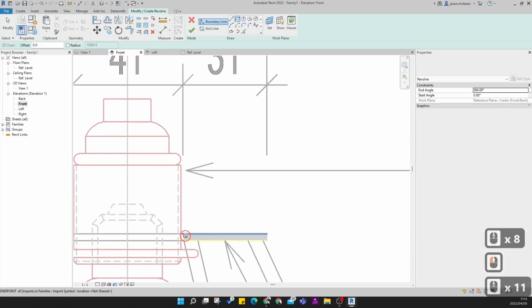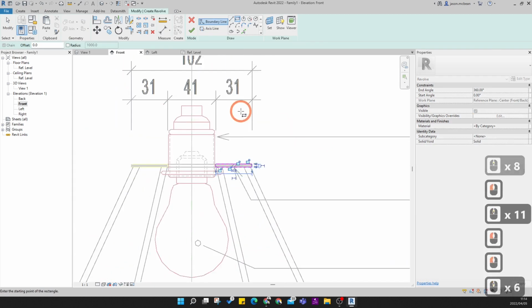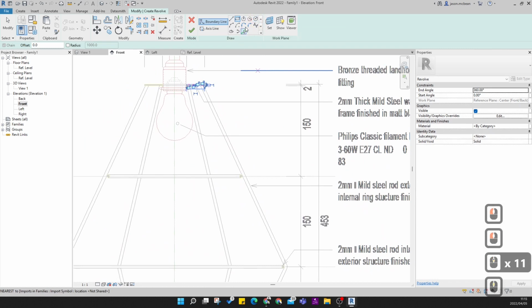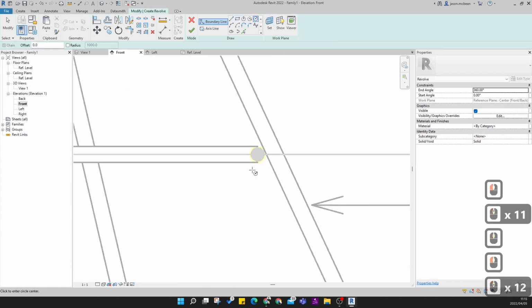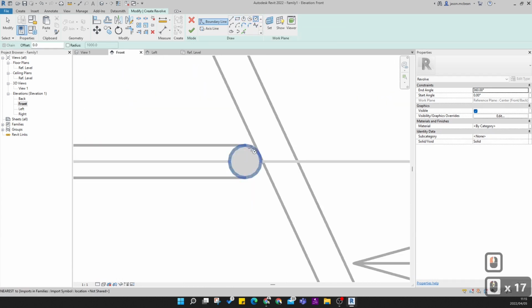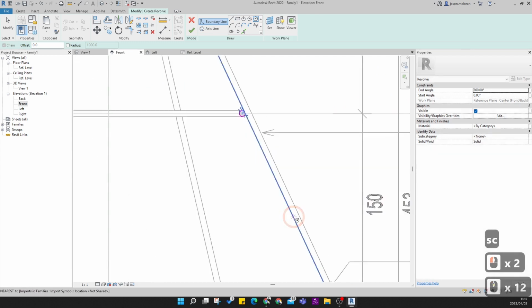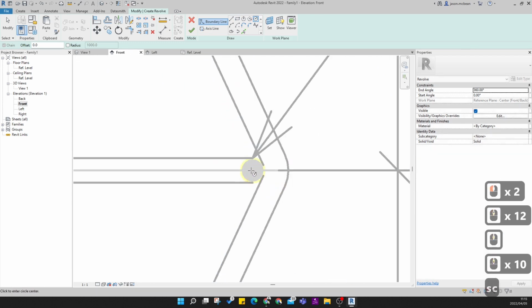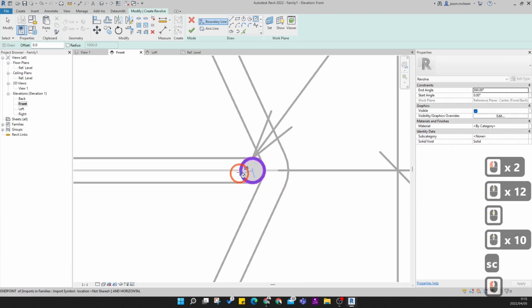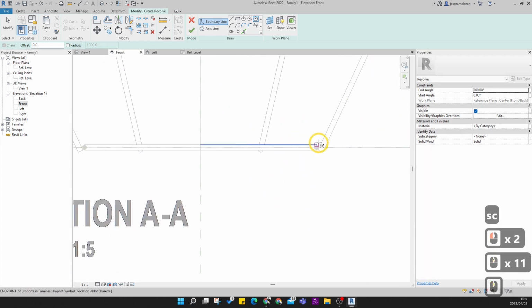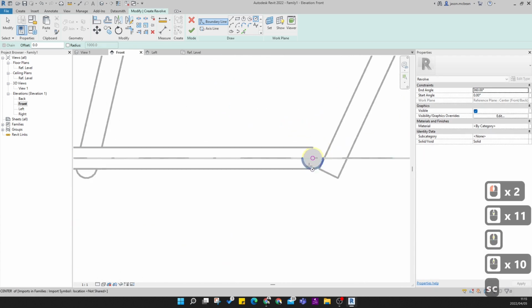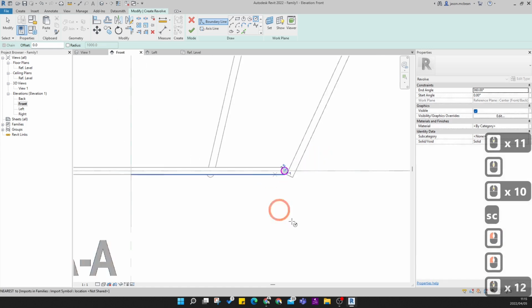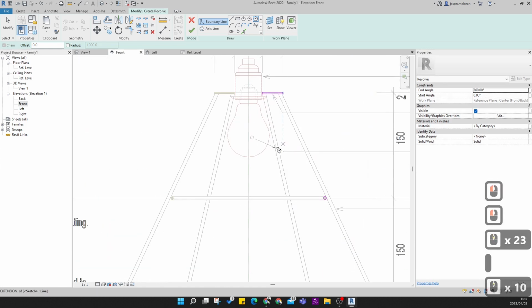This will be pretty straightforward. It should snap onto these objects. Now I can use a pick line tool, but I'm just going to use a circle tool for this. And it will also snap to the center. Snap C, snap center. That's how you switch it on to snap center. So likewise, snap center. Okay, snap center.